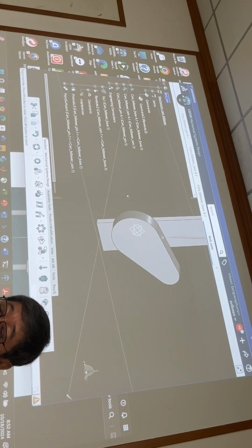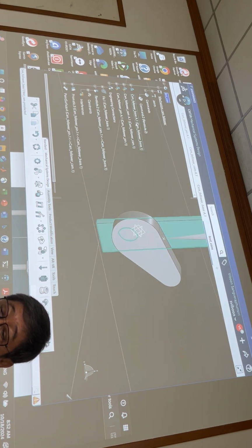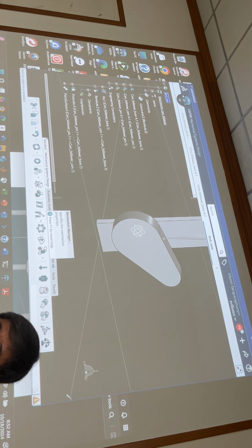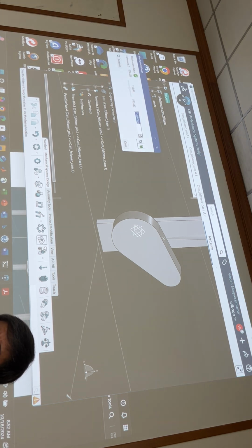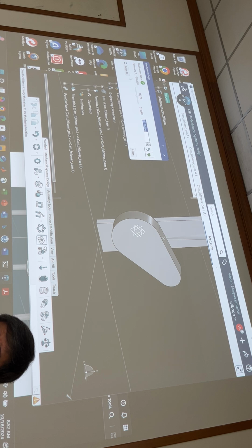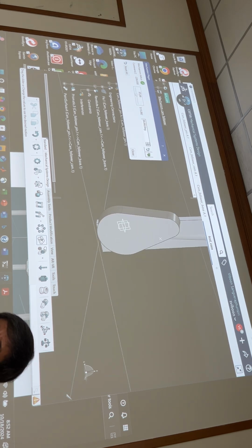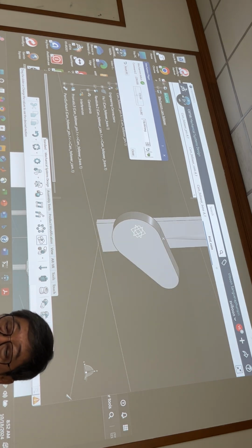Once you have this one, everything is okay. You already checked from the mechanism manager. You can use the mechanism player. This one, right? Mechanism player. So this is a command. You see this one, right? If you want to set the angle, lower limit and upper limit.